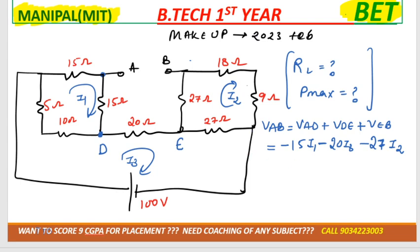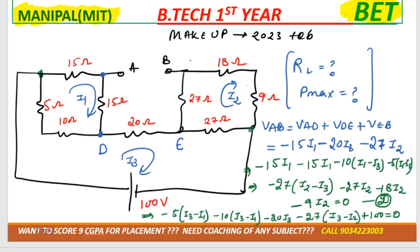Now you need to make mesh equations. Now you'll have these three mesh equations, I1, I2 and I3. You can solve this. Then you can substitute the values of I1, I2, I3 over here. Then after that you will get the value for VAB. That will be VTH. But after that you need to calculate resistance also, right? That is RTH. Correct? So how will you calculate RTH?